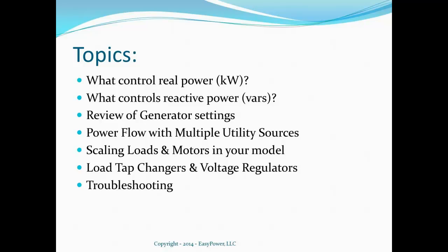And so when we run power flow, this is not the same as doing our load calcs for sizing cables for the National Electrical Code or things like that. This is strictly an attempt to simulate the actual conditions in your power system. And normally we're worried about specific conditions like peak demand periods and maybe minimum demand, that kind of thing. But we need to scale the loads to simulate those.